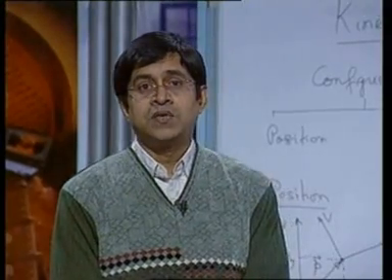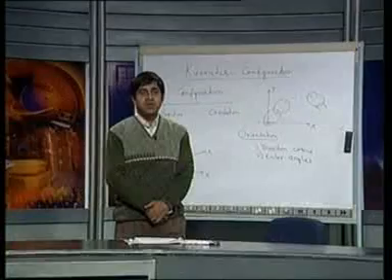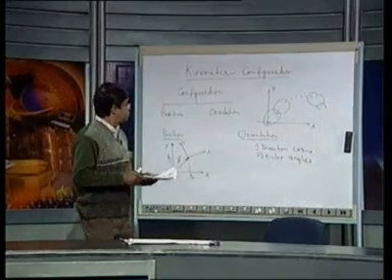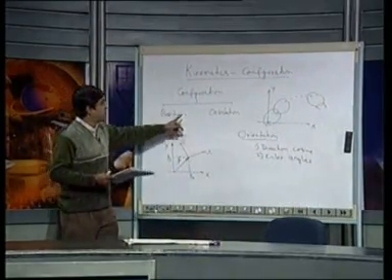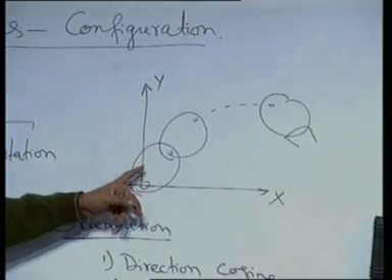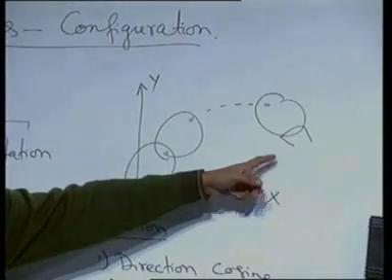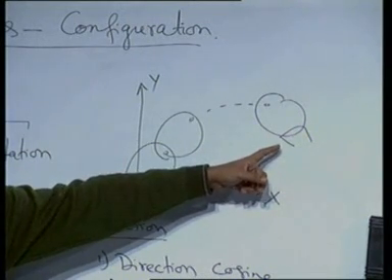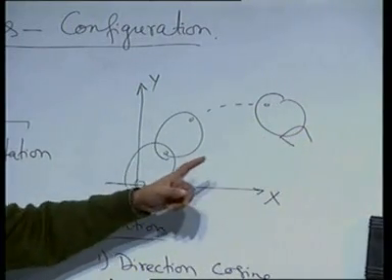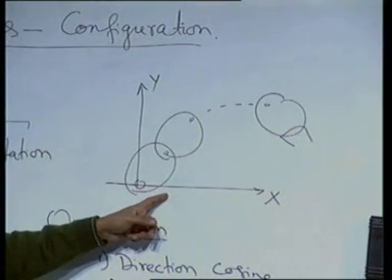Good day friends, now I will discuss the configuration of a rigid body, which is a part of the kinematics discussion. When you talk about configuration, it includes position and orientation. Why is it required? In a robotic system, for example, there are many bodies here and this is the end effector of the robot. You want to control it by specifying the x, y, z coordinates of, say, the end effector. Now, we want to correlate what its motion is with respect to the fixed frame here.